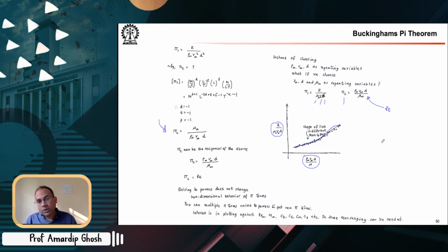So someone who doesn't have an idea of Buckingham's Pi theorem or dimensional analysis and similitude might end up running experiments and reporting a lot of dimensional variables plotted against some other dimensional variable, holding some dimensional variables constant. That would lead to a huge amount of effort and difficulty in interpolating or extrapolating data.